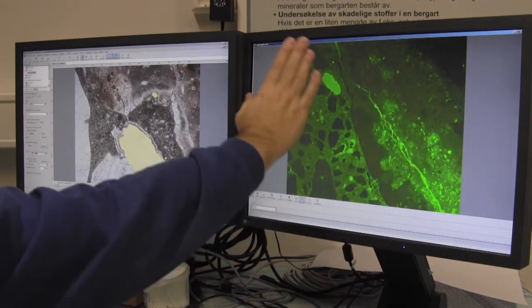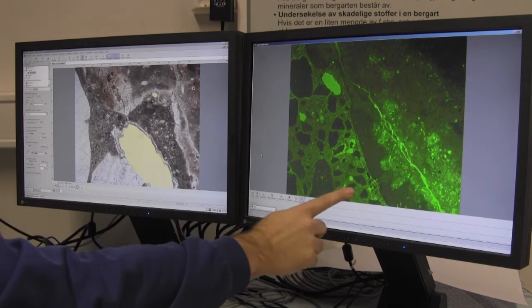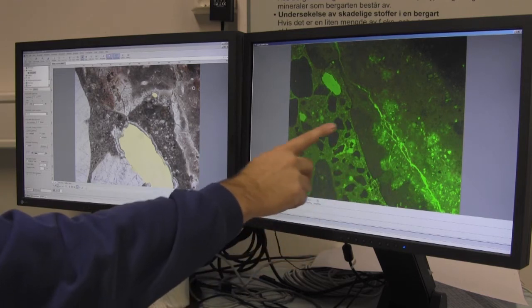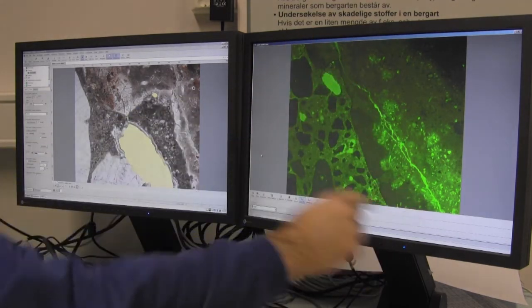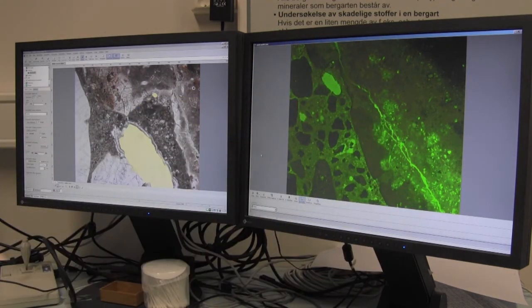This is the aggregate grain, and this is the rest of the concrete with the fine aggregate particles, the sand. And you can see that this crack is breaking up the interior of the large aggregate particle. That is only one type of damage, which is particularly devastating, because structures cannot really be repaired and have to be replaced. So if you have that kind of damage, it's going to be very expensive.